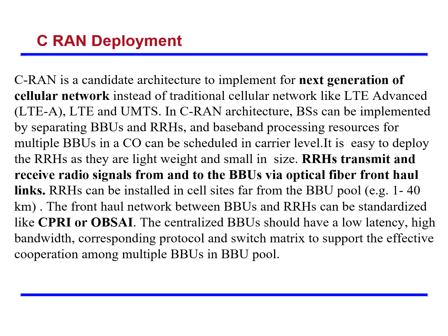In CRAN architecture, BSs can be implemented by separating BBUs and RRHs, and baseband processing resources for multiple BBUs in a CU can be scheduled at carrier level. It is easy to deploy the RRHs as they are lightweight and small in size.